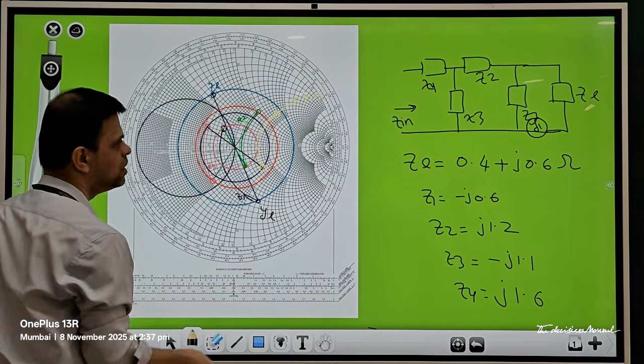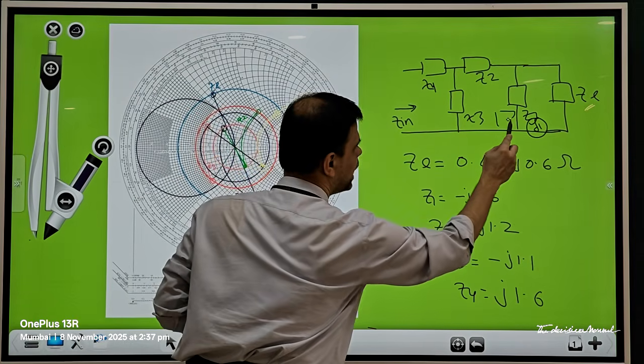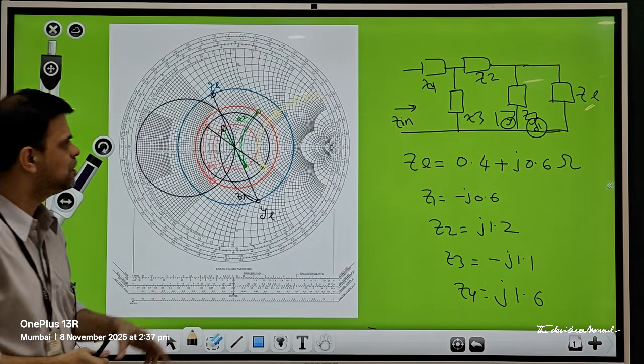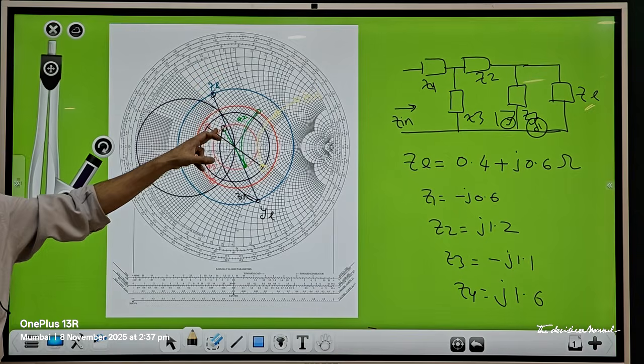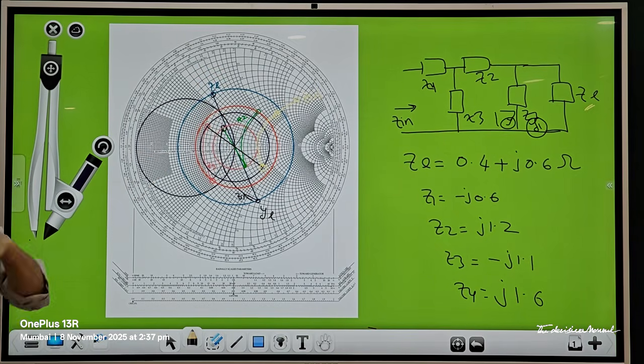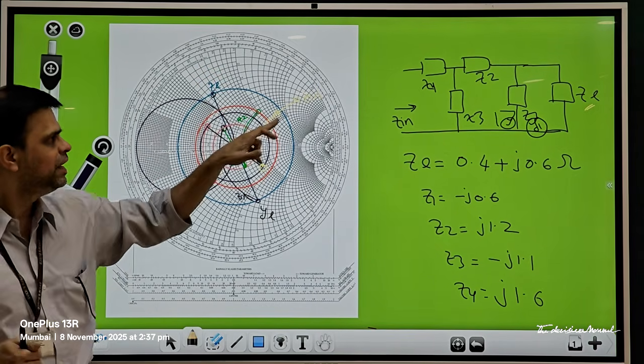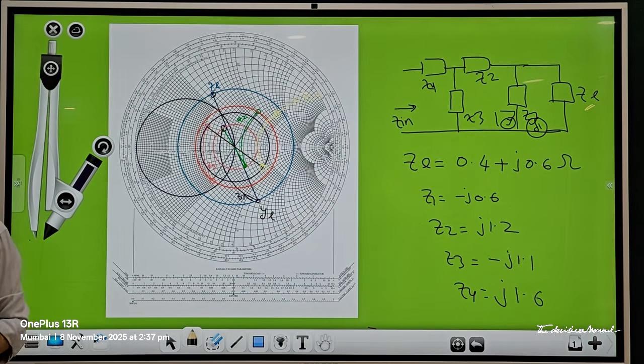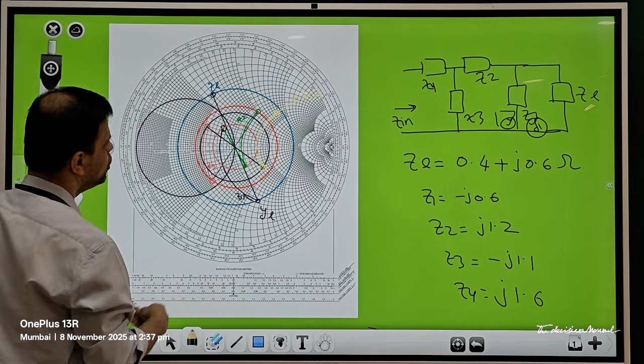Okay, so this is the admittance at that particular point. What next impedance is coming? It is Z2, which is in series. Naturally, you cannot work on Y domain. You must go back to the corresponding Z domain. So what you will do?